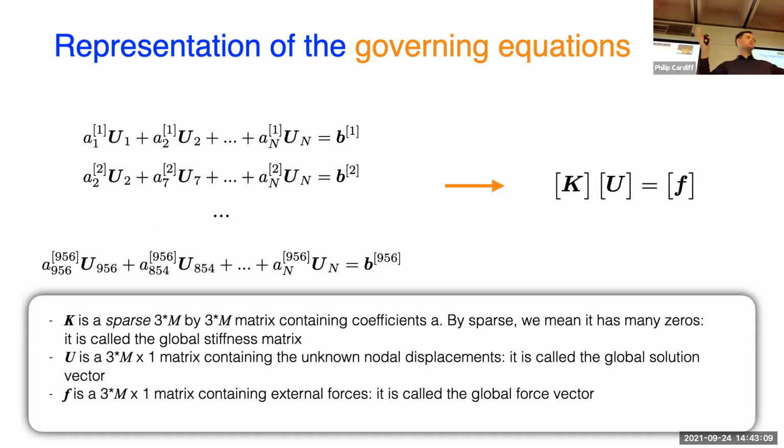If I have this giant matrix, each equation only has like 7 nodes in it. It doesn't mention all 1000 displacements. So it's just like 7 non-zeros in any row, depending on how many nodes there are. That means it's mostly zeros. And then U is the unknown. If we have n nodes, 1000 nodes, then this matrix would be 3000 by 3000 because of 3 unknowns.